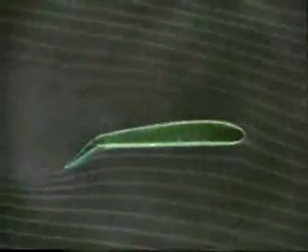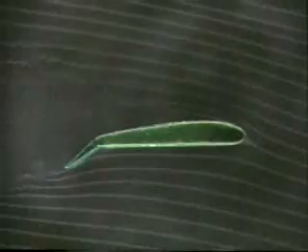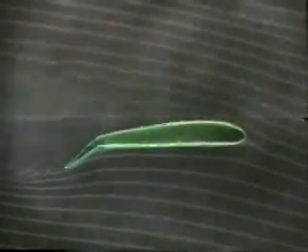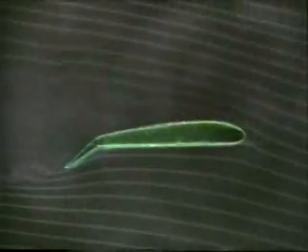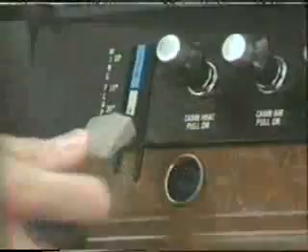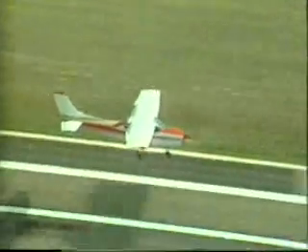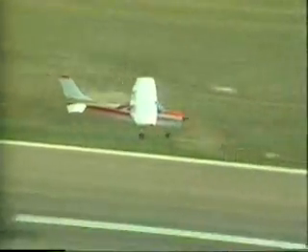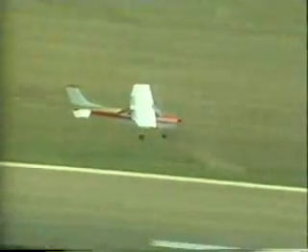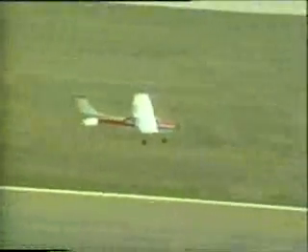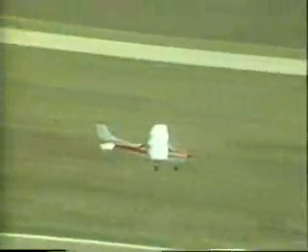However, flap deflection beyond approximately 50% of the flap range produces a greater change in drag than lift. Now, drag has a greater influence on the airplane than does lift. After applying power for a go-around, you must adjust the flaps to the manufacturer's recommended setting, since the drag generated by full flap extension produces a drag coefficient that outweighs lift. If the flaps are not set properly, the airplane's climb performance is well below its maximum capability. In extreme cases, it may not be able to climb, or may continue to descend, even with full power applied.